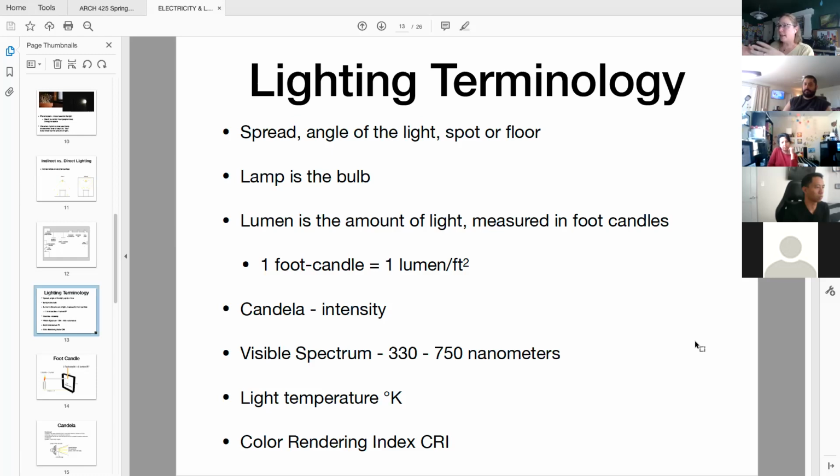When you're looking at a lighting design, and we'll get there in a few more slides, you're looking at how far that light fixture is going to illuminate a surface with what level of lumens, 5 feet from the fixture, 10 feet from the fixture. This makes a big difference if you're looking at pendant lights or recessed fixtures.